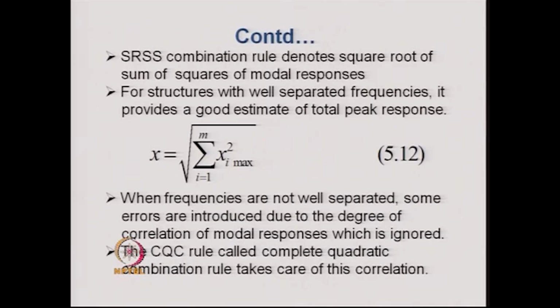So, equation 5.12 is developed with the assumption that the maximum values in each mode of vibration are independent random variables, and they are summed up with the help of the SRSS rule.